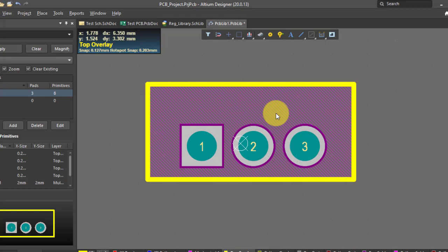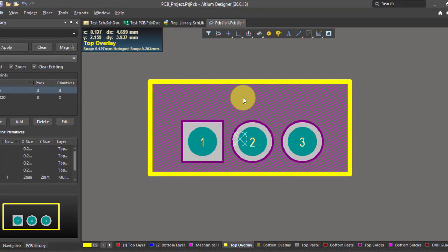We should make sure that none of the components on the PCB is inside this range. Because we know that once the regulator IC is soldered in, it will take this much of space, so you cannot place a component within this boundary. But if you want to put that IC on the top, you can then put another component inside this boundary at the bottom.